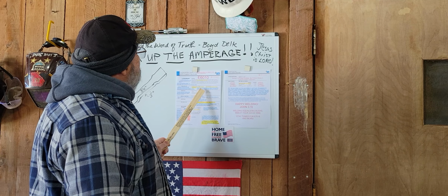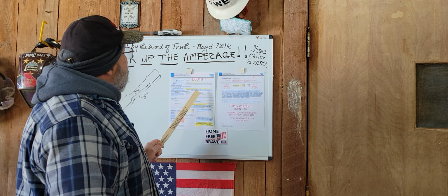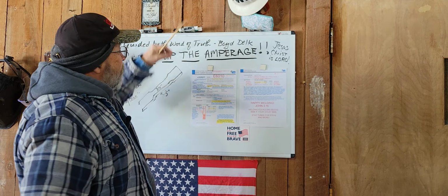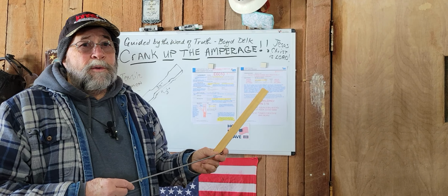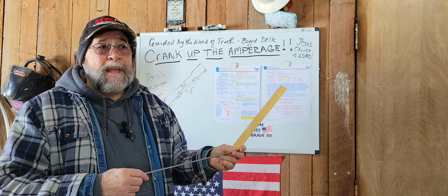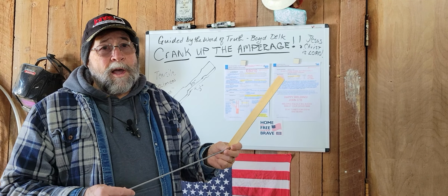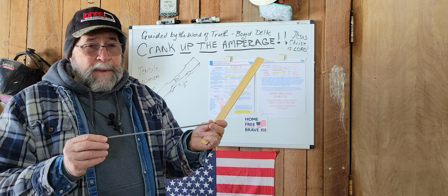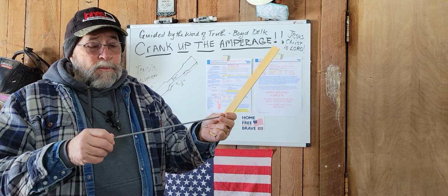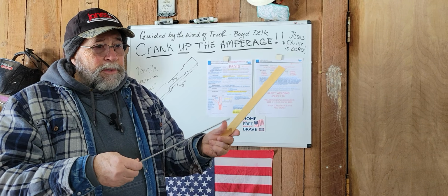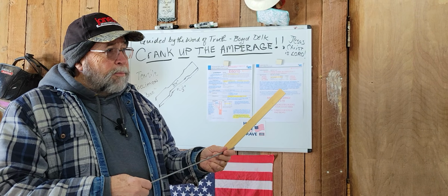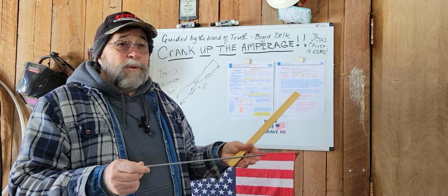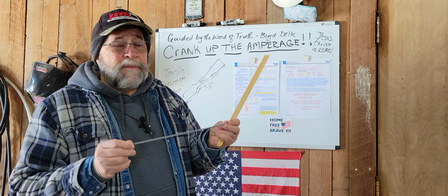So deep penetration, 100% penetration for root passes, and it does not need to be stored in a rod oven. What that means is that, for example, a 7018 electrode, a low hydrogen rod, has to be stored in a rod oven to keep moisture out of the rod for best function and best quality of the weld. These are designed paper-based. They actually run better with a little bit of moisture in the environment. You can lay those over there on the table or put the box of welding rods up on the shelf and just leave them open in the atmosphere. And whenever you need them, just go grab them down and use them, and they work perfectly fine.